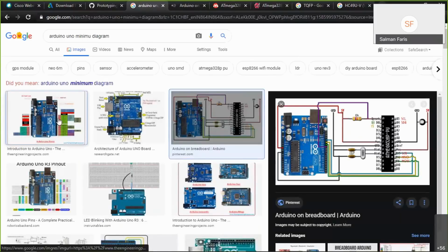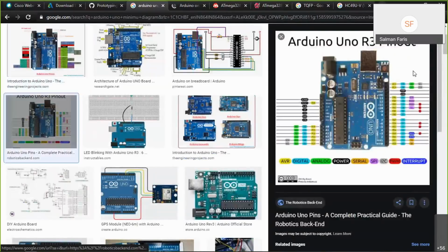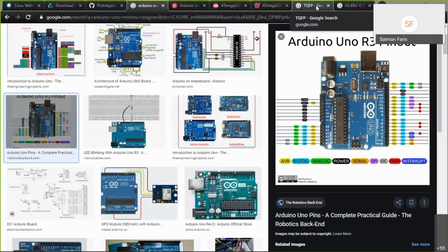And the funny thing about Arduino is that the crystal here is actually not related to this one. This clock is actually related to this controller. This is actually an ATmega32U4, the main microcontroller. For this, we are using this clock. You can see an assembly version of the clock. You can see also a capacitor here. For this circuit, actually a programmer circuit, it's converting the USB signal to ISP, in-circuit serial programmer. Fine.